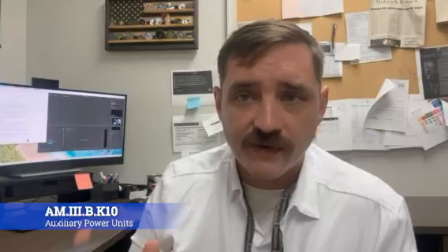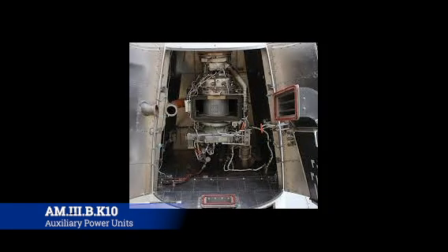All right, lastly, let's talk about auxiliary power units, or APUs. Where do we find them and what are they for? Okay, lastly, we're going to talk about the APU, the Auxiliary Power Unit. And all this is a very small jet engine, usually located in the tail of the aircraft, that helps supply ground power whenever the engines aren't running. So it has a lesser fuel burn, but it still supplies enough electrical and air and hydraulic power to the different things on the aircraft that you may need for maintenance or to cool the aircraft off before somebody gets on board.